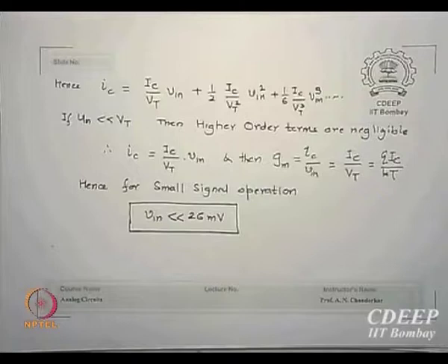Is that clear? I explained it in two ways. One is from the transfer characteristic, where you will get harmonics out. Even without that, with normal thinking, I can prove that I cannot exceed too many, because remember Vin will be sin omega t. Sin square omega t means 2 omega t, omega 1 plus omega 2, omega 1 minus omega 2, third order terms will start appearing.